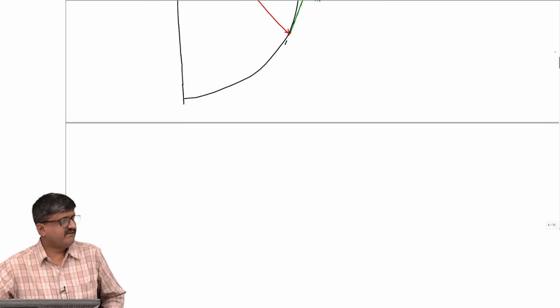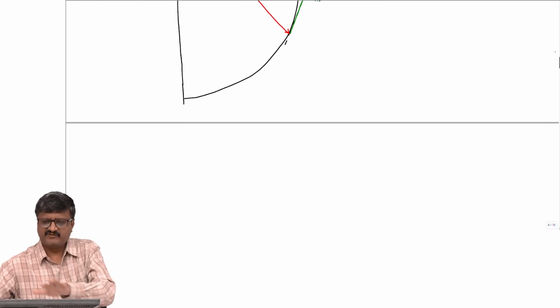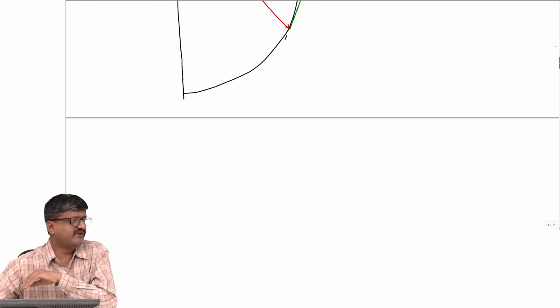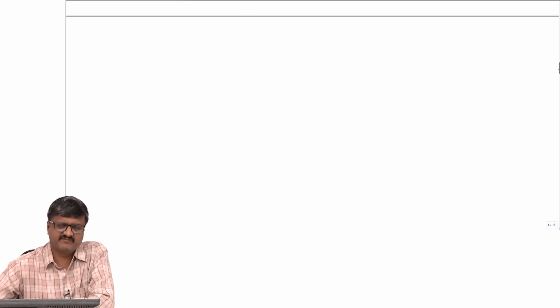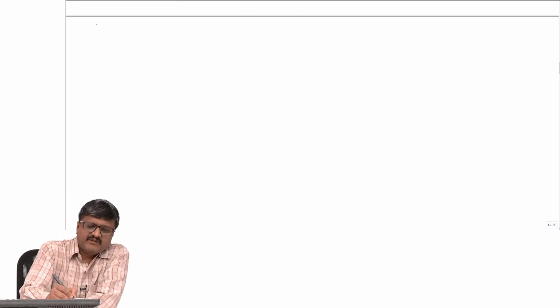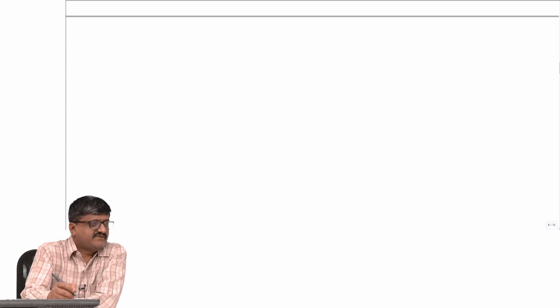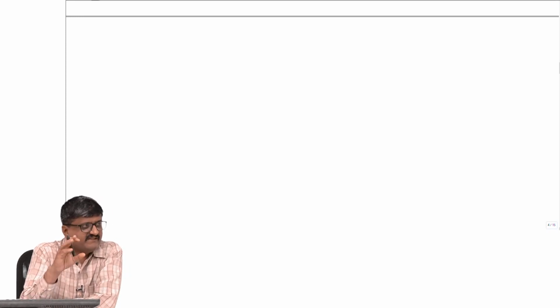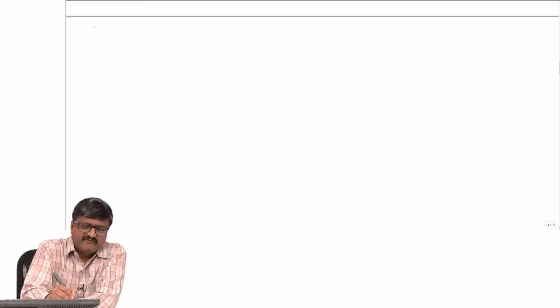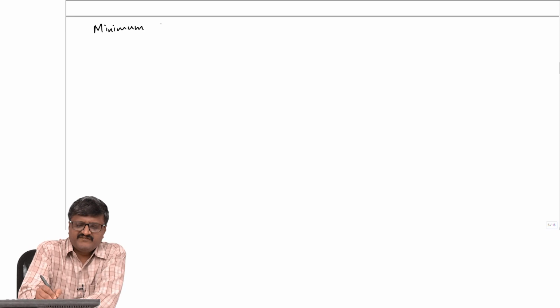So far we considered performance. So, these are the things which have to be done in order to meet the performance or maximize the performance. Now, we will see how to actually do further design. I mean, we have not completed the design. See, design is completed only when we have the value of RLC. So, for that we will minimize the cost and get the values of R, L and C, minimum cost filter.